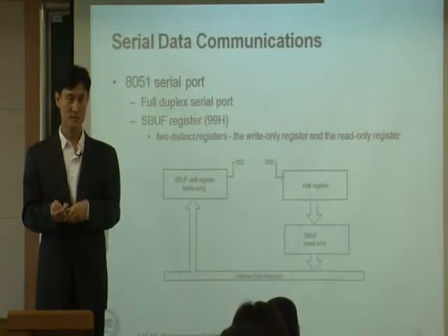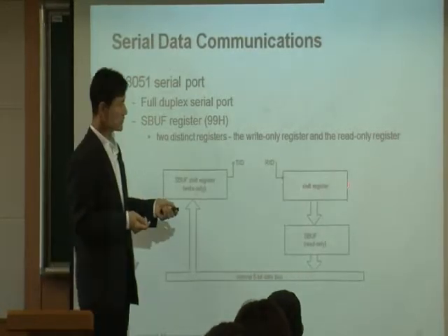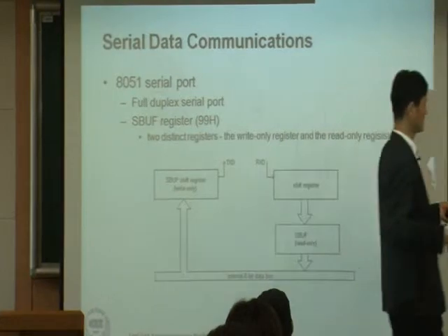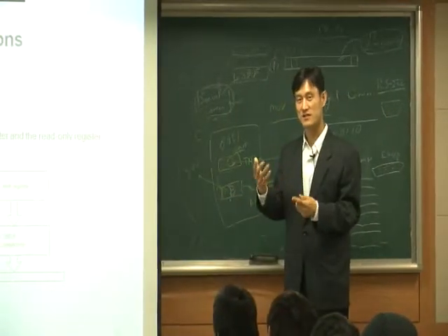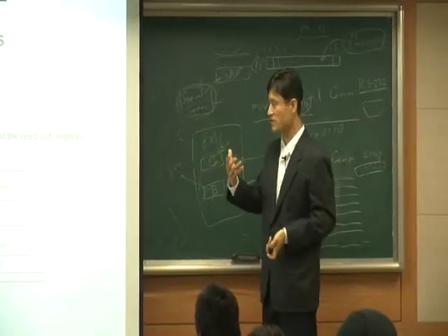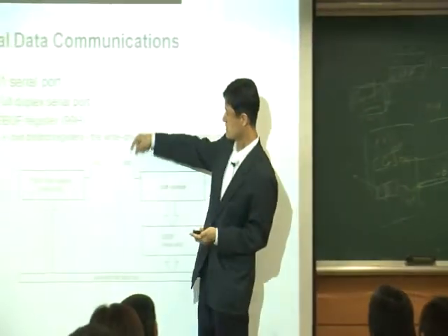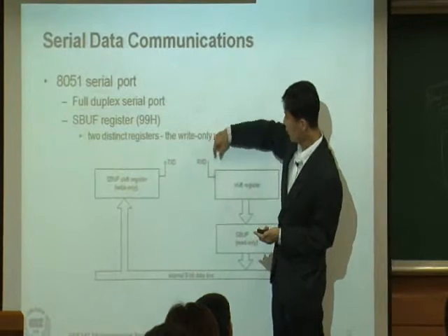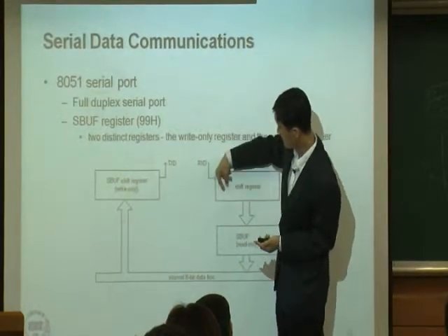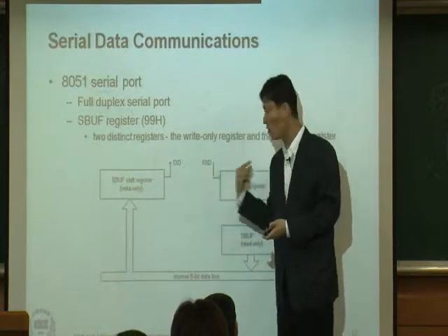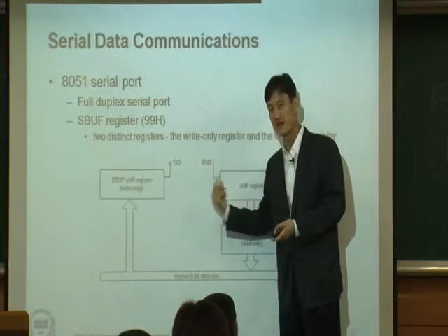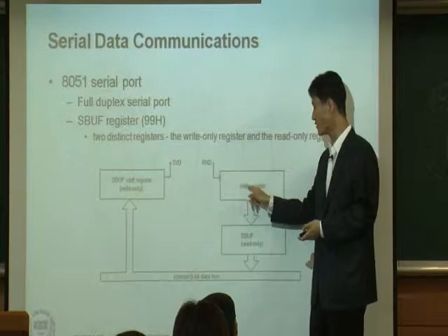Why is the shift register in there? This one is actually serial communications. So you have bits, all the bits on one line, one bit after another bit, after another bit. Those bits, all serially coming in, go into the shift register.